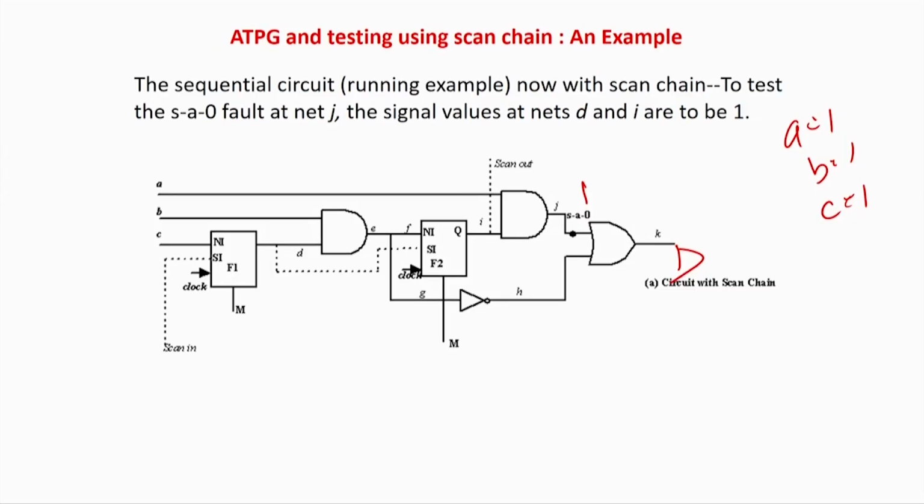Like here I am calculating C equal to 1 will make flip flop 1 equal to 1, but I require some mathematical calculations to find out that B has to be also equal to 1, and in the next stage flip flop 2 will become 1. So, with a more intertwined circuit, you can find out that it is going to become a more complicated binary equation solving kind of problem. But anyway, now we have the story of scan chain, so it is simple.